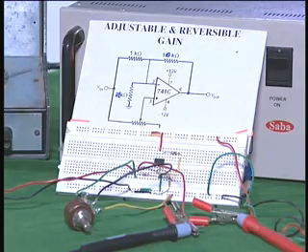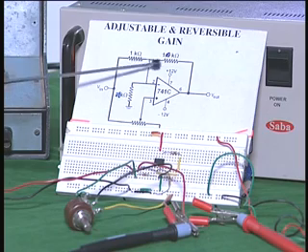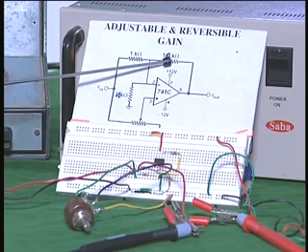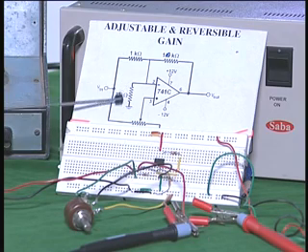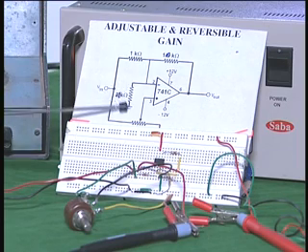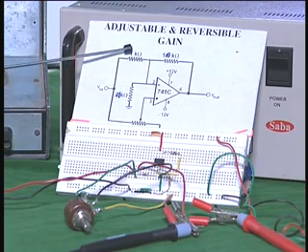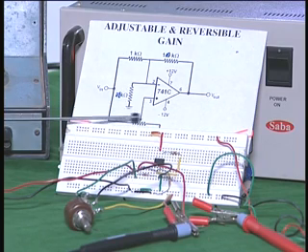Now, you can see the circuit here, it is the same as what I have shown you earlier. So, I have NR is 10k, the R is 1k, therefore, n is 10. This is 10k resistor, this is 1k resistor, and this is n by n minus 1 times R, and because n is 10, 10 by 10 minus 1 is 9, 10 by 9 times R, R is 1k, therefore 10 by 9 is nearly 1k, therefore I have put it as 1k. So, this is 10k, this is 1k, this is 1k also, and here I have a potentiometer which can vary from 0 to some value, usually it will be a 1k or 2k resistor here.